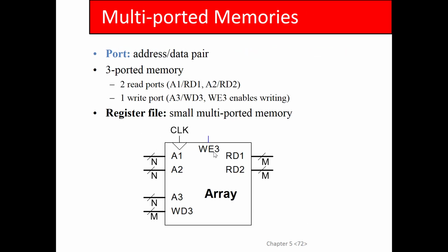Multiport memory is when you allow multiple reads and writes at the same time. SRAMs sometimes have multiple ports, caches. Makes sense, right? Because caches are shared by multiple cores sometimes. So if you're sharing a memory, you need more ports, but more ports increases the cost dramatically. DRAM generally only has one port. So you can read or write, but not at the same time, and only one access at a time on even a modern day computer.